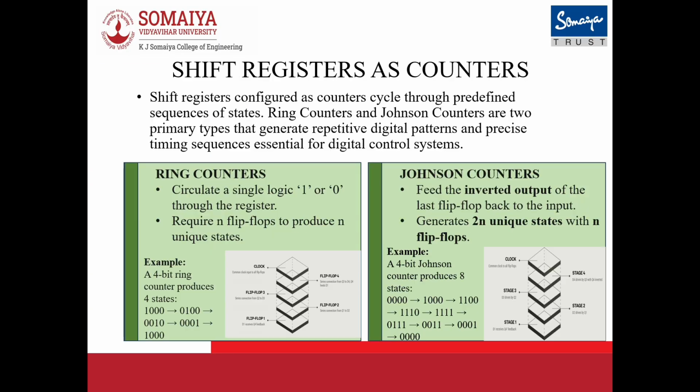Now, shift registers as counters. Now let's move a step ahead. What happens when we configure this shift register to behave like a counter? Normally, counters use combinational logic and flip-flops to move through a binary sequence like 000, 001, 010, and so on. But when we use shift registers as counters, they generate special patterns of logical sequence that are extremely predictable and repetitive, perfect for timing and control systems.